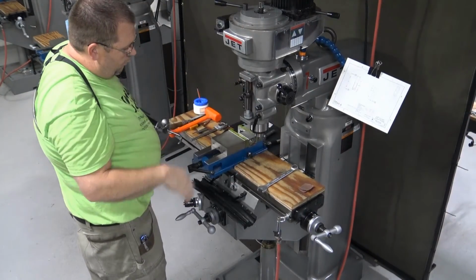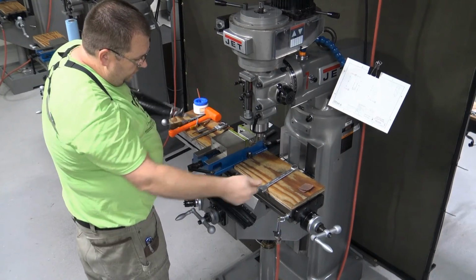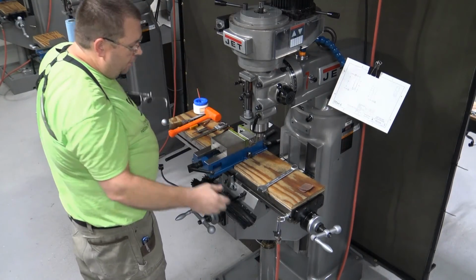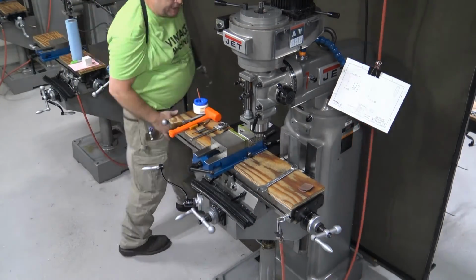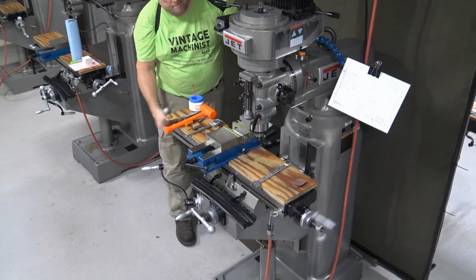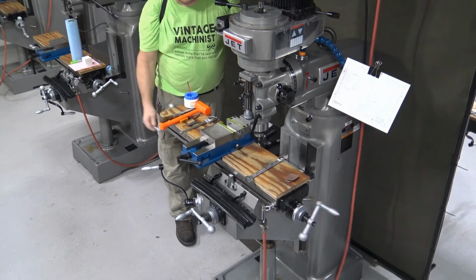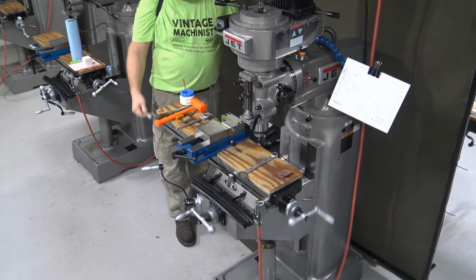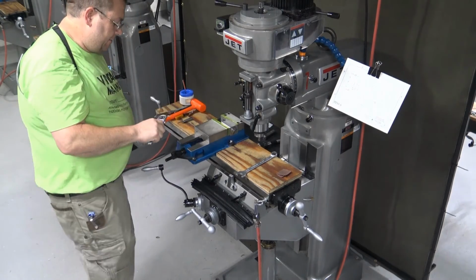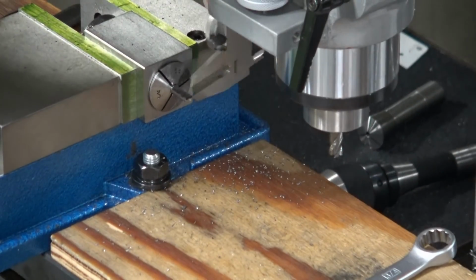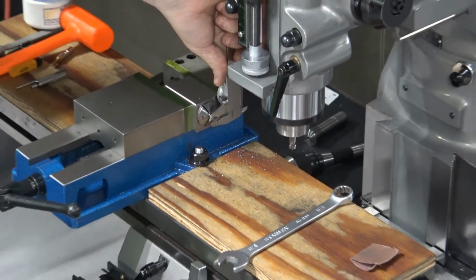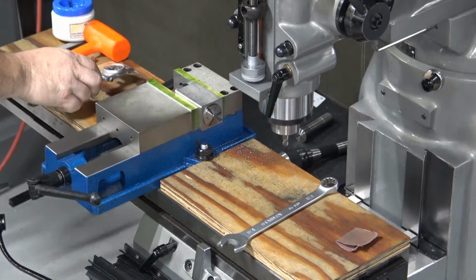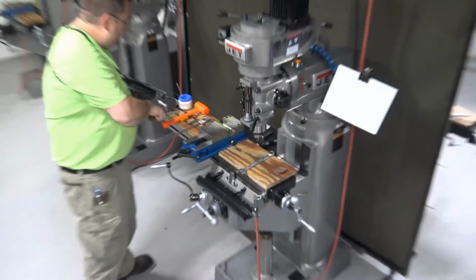Start my machine. If I loosen the quill up, pull it up out of the way, I've lost my zero. If I change the dials or if I take the part out, I've lost my zero. So what do we think that we want to do before we change any of our setup? What I want to do is I want to measure one last time that 170 to 175 dimension. Make sure I zero my calipers. Look at that. Just a touch over 172 thousandths. I feel real good about that.